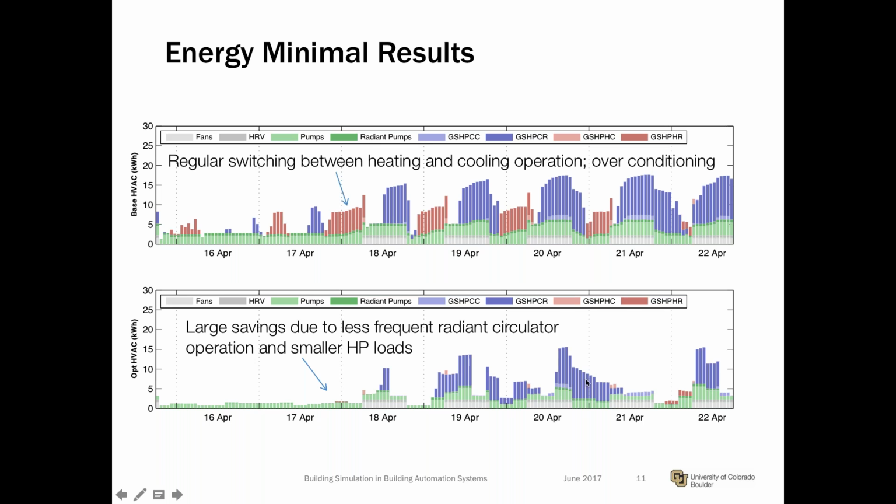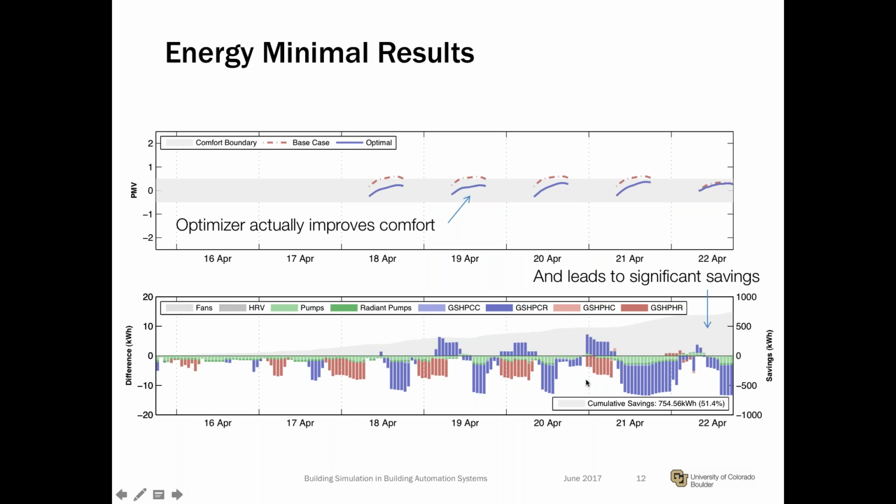So how's the building performing from a comfort perspective? What we see here is that the building is on the basis of a PMV-PPD, predicted mean vote, percent people dissatisfied model. We are keeping the building in the gray zone. That's the plus minus 0.5 zone that ISO 7730 suggests. Whereas the standard building seems to exceed the indoor conditions, tends to be slightly warm.